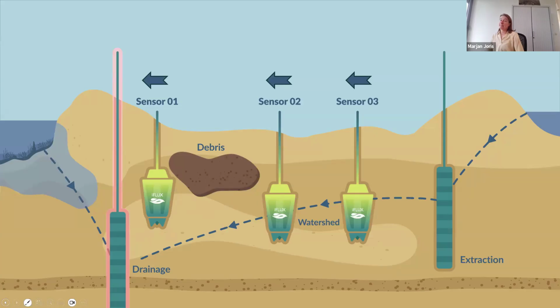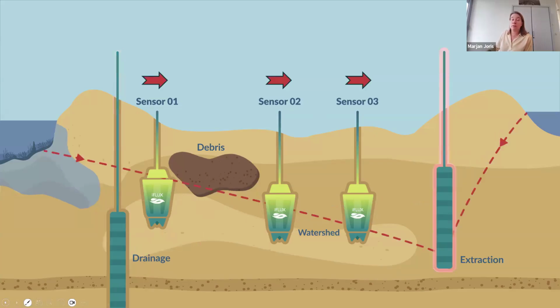In the less ideal case, the protection wells are over-extracting, and fresh water is pumped by the protection wells, and water is getting lost, which is not the objective, of course. But even worse, and what the drinking water company absolutely doesn't want, is that salt water is intruding the freshwater supply, or the contamination.